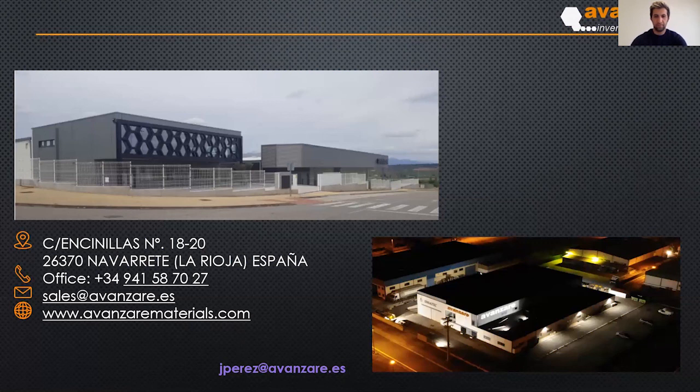But on the market, you can find graphene oxide, which means that over the surface of the graphene, there are some oxygen atoms. There is also a lot of exfoliated graphite that is named graphene. And there is GNP, graphene nanoplatelets, with a thickness of, for example, 6 nanometers to 30 nanometers. The cost of everything changes completely.